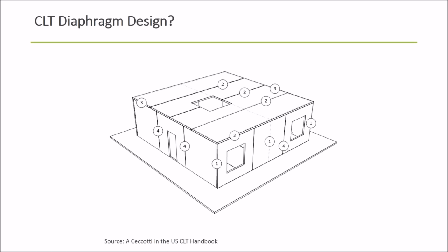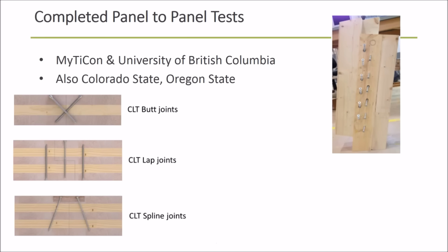Again, our actual panels themselves are very stiff and strong, and it all comes down to connections. And if you start to get into these mass timber designs and these mass timber products and CLT design, really spend some time understanding the different connection technologies and their behavior.